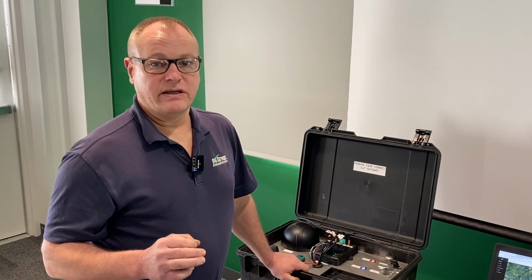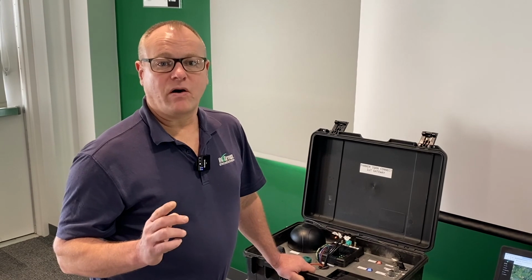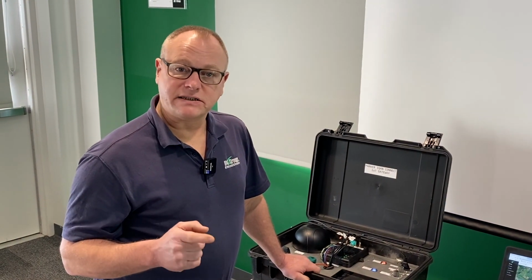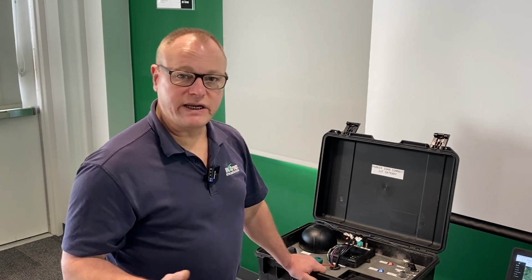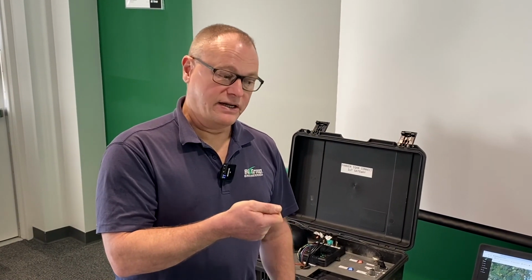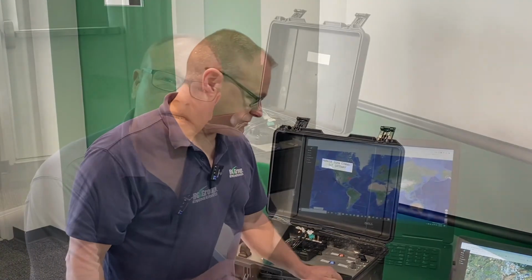So they speak J1939, which is an SAE standard for automotive diagnostics and chassis information, vehicle speed, DEF fluid levels, anything and everything you can plug a round connector into a truck chassis. If you're familiar with that, with your laptop, you can now do that remotely and that data streams. So there's a lot of information that you can get sitting at a remote location with a computer.